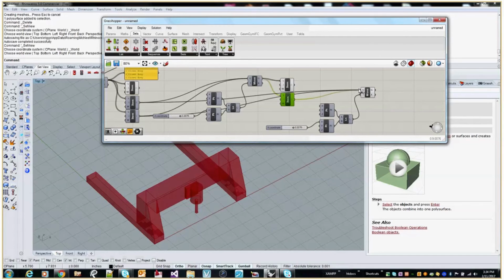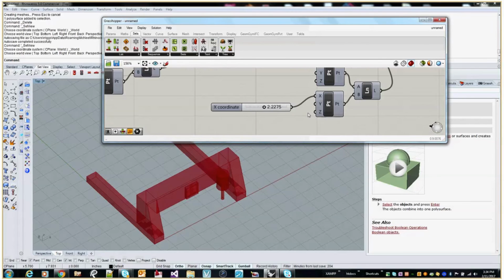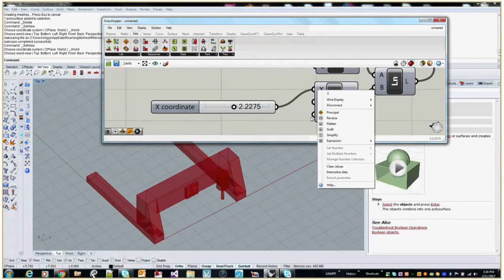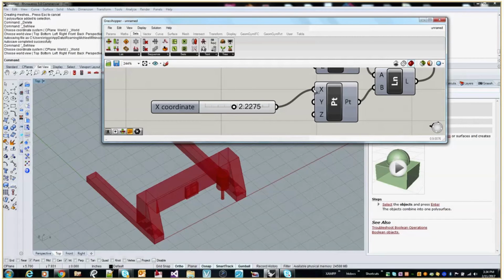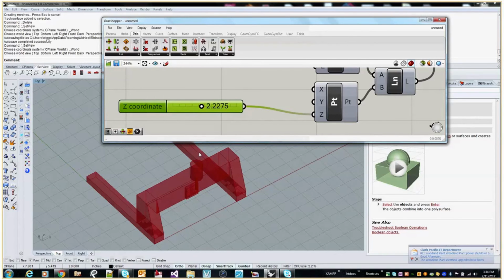And then what we're going to want to move here is this guy, but we're not going to want to move it on the X. We're going to want to move it on the Z axis. So I think if I hold Control, there we go. If I do Control Shift, I'm able to move the input, and that updated to the Z coordinate. The problem with this particular one is I don't want to go up. I only want to go down, and as you guys know in CNC land, Z up is positive, so it's doing the right thing.